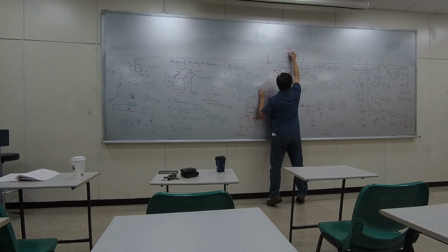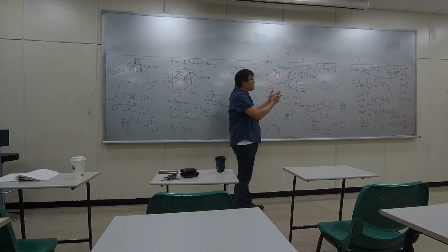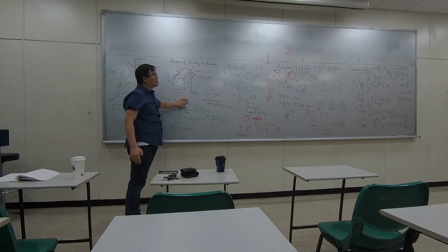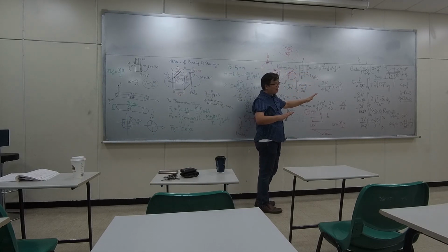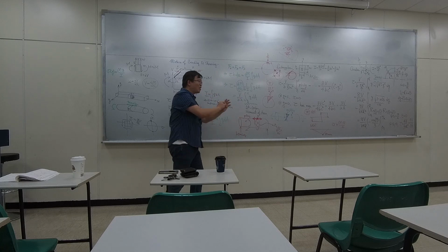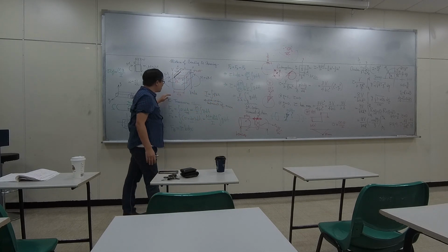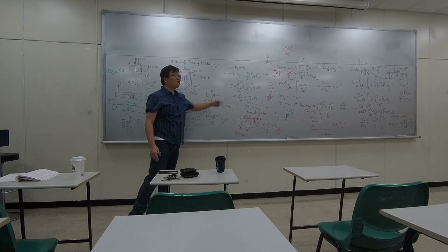The torque is like this, and you're fine because it's still stresses on the plane. However, when transverse shear comes into the story, you are introducing stresses in a different plane. It's no longer a plane stress problem. It's something I don't want to deal with. So in that particular homework, I should add one more sentence, assuming transverse shear to be 0. Otherwise, you need to work on it.